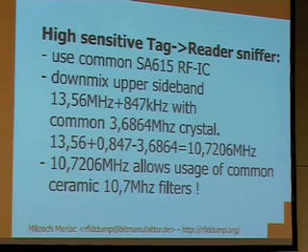What we have done, we used the commonly available RF down mixer, where we take this 13.5 megahertz and mix it down to a frequency where we get freely available filters. The point is, filters are only available at very few frequencies, so it's practically not possible to have custom ones built. So we have to live with this disadvantage and tune it to a frequency where we have filters available.